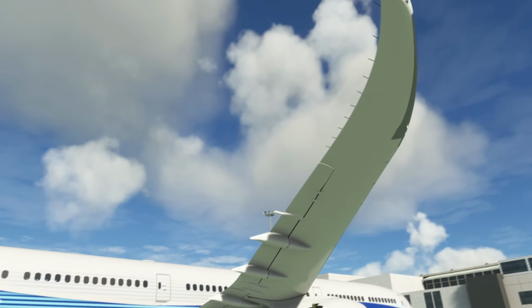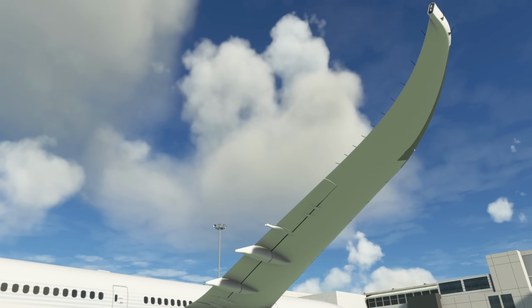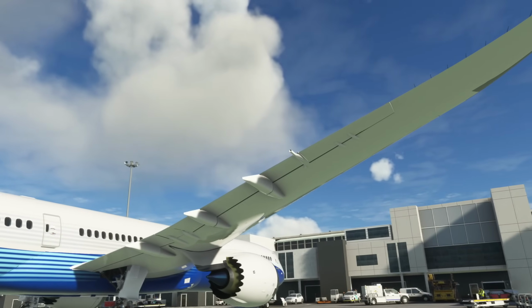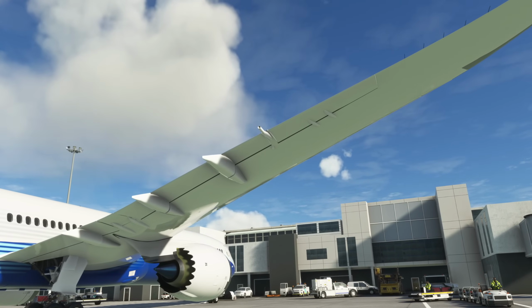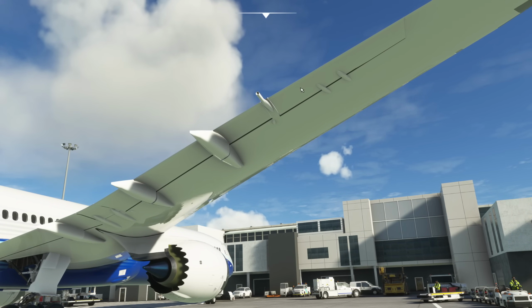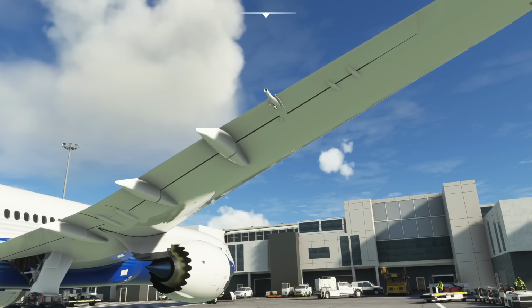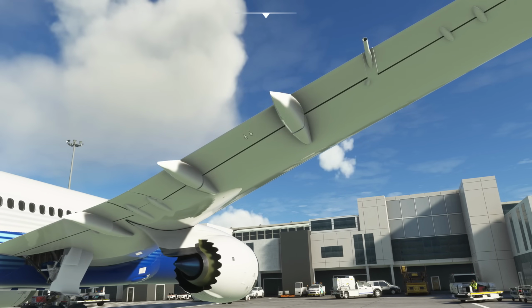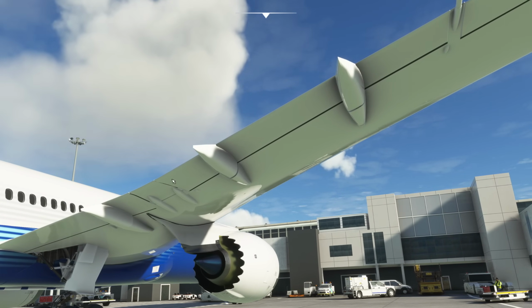That's what we have. So there's no aileron out there. It looks like it should be out on that edge bit, but it's not. That's just sort of, I don't want to call it dead wing, but yeah, it is not used for much. This is our outboard aileron. We get 2 ailerons on the 787. So one out here. Then we have the fuel dumping or fuel jettison system. Hopefully not needed, but that's where it is. And then our flaps. Very simple, single slotted flaps on the 787.